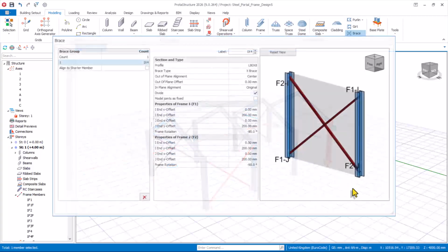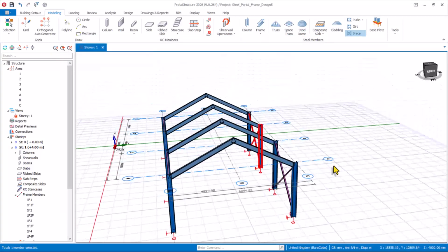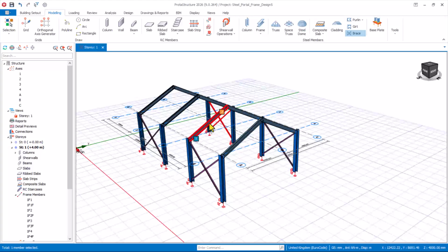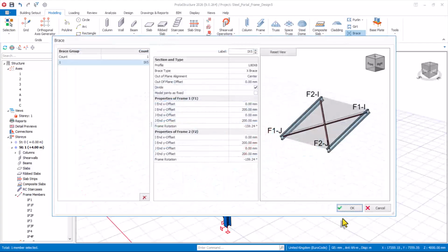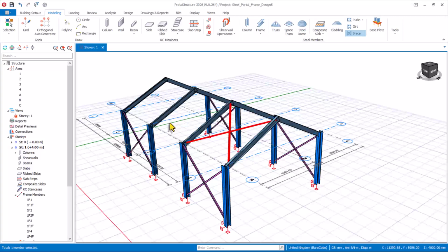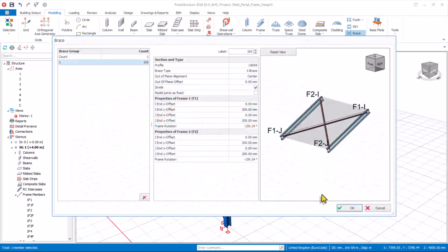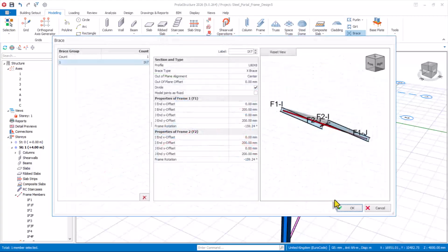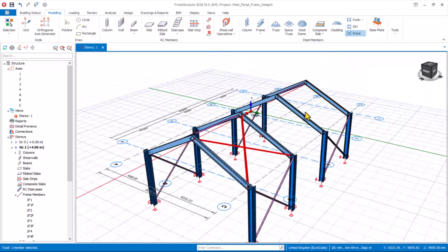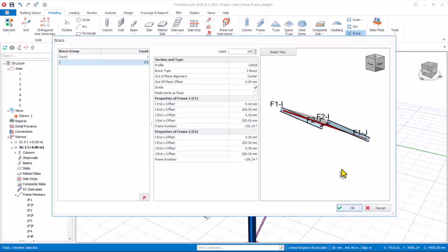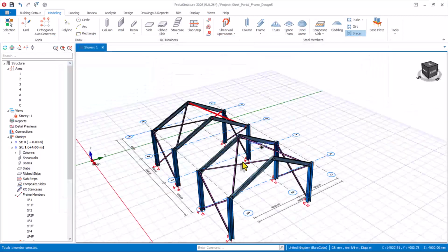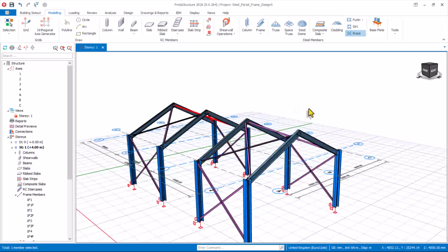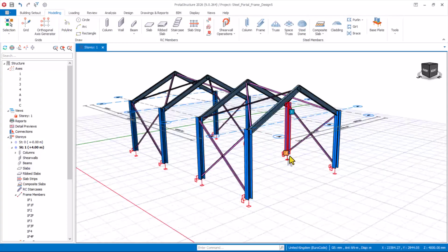and then between these two stanchions, so we also have brace at the roof. So we just have to select the two beam rafters to have it placed, just like this. Just have to brace the members. So this is basically the wing brace. We are just applying it on this roof. Okay, so I click on the OK option. All right, so at this point we proceed to actually model the purlin. So I'll save this model just like this, and we proceed.